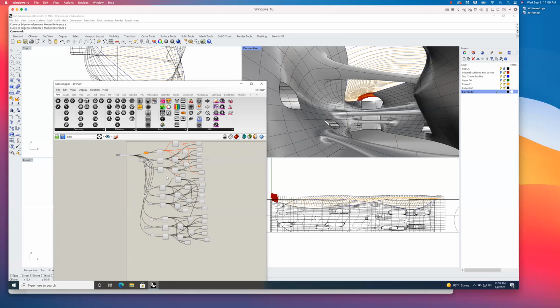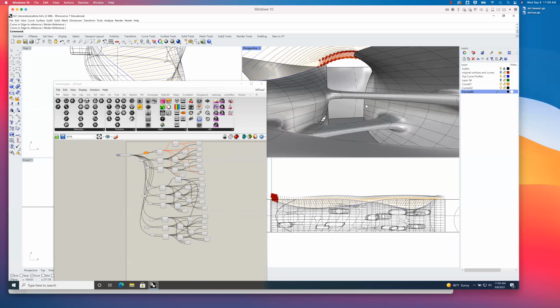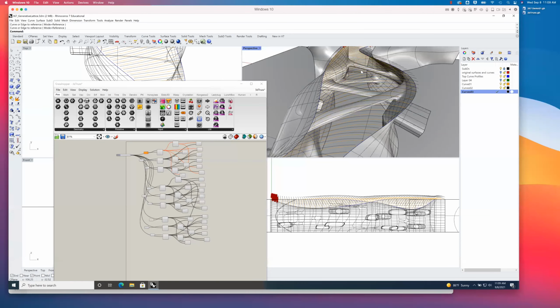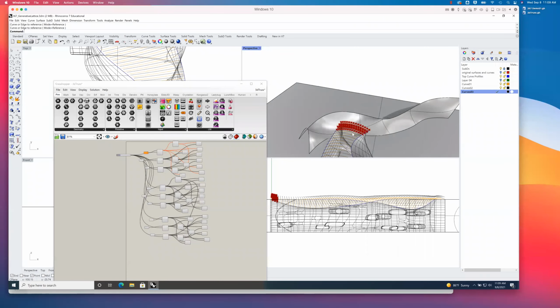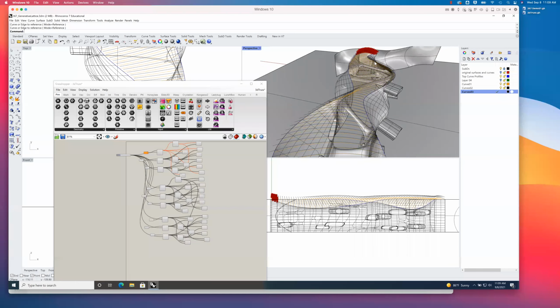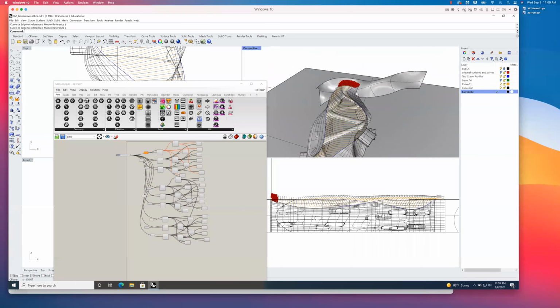All right, so again, this is several different ways you can begin to take those curves and generate some typical trusses between them, or what I think is better, generate a surface. There's lots of different ways to generate a surface across the roof, and then use that surface to extract its wireframe after you rebuild it, right? So you get a critical mass of chords you can use for the appropriate amount of trusses, which, this is quite a long expanse here. So you're going to have 60 or 70, or maybe you need 80 of these, right?